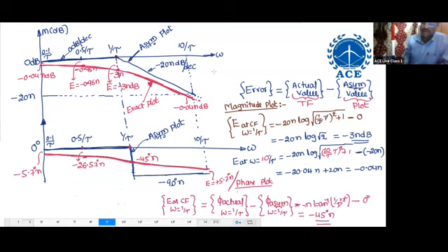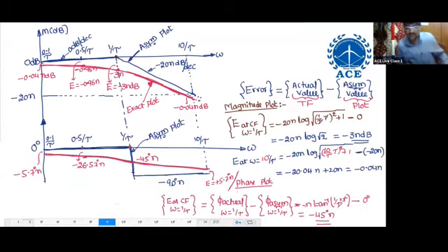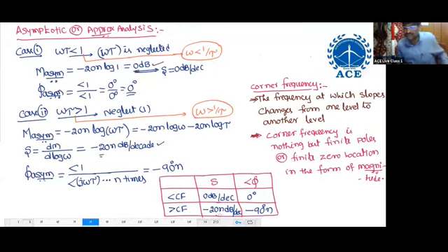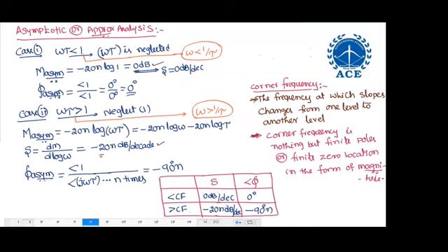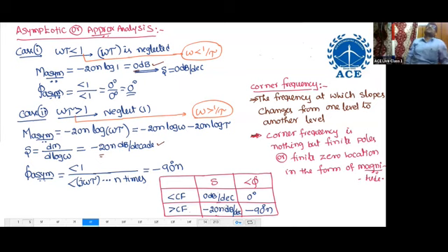So at the end, only doubts. Next, go for the note on the problem: N finite zeros homework. Do the homework. Finally, what you have to remember is poles give the slope of negative 20n and phase angle minus 90n. Zeros give the slope plus 20n and plus 90n. Remember that. Okay.